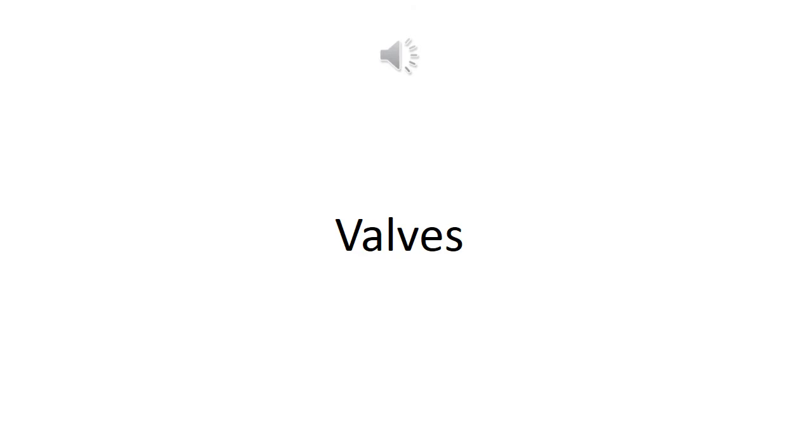On the valves, they will have the term WOG or WSP, or they could have both terms imprinted on the valve along with a number. What WOG stands for is water, oil, or gas. The number is the pressure at which the valve is rated. WSP stands for working steam pressure. The number is the pressure at which the valve is rated for. Valves rated for steam could also be marked SWP or with just an S.